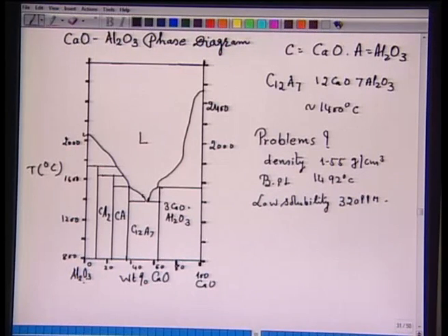All the advantages I have told you about calcium addition have led to the development of a technology to make calcium available in the steel bath, because whatever calcium you add will float and oxidize, and it will not do your job. So, it boils down to developing a technology to inject calcium deep into the bath, at least up to a depth where the effect of vapor pressure is minimized. So the question comes: the technology, and how to add.